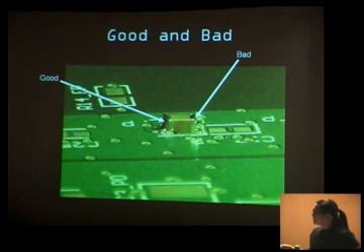So here's an image of a good and a bad connection. Here you can see the solder's formed a good bead on the pad, and here you can see the solder formed a bubble on the edge here and no contact to the pad whatsoever because it's not going to heat up the board enough, right?